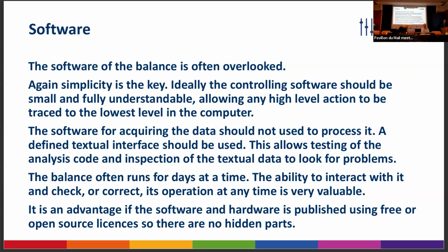Secondly, you shouldn't acquire data and process it at the same time. It's much better to acquire it, output it in a standard interface, and then do all the processing separately. So you can use several different programs and make sure that all is well, and keep the thing that's acquiring the data simple. Also, you've got a balance that runs for days at a time. If you can't access it while it's running, sometimes you get real trouble. I find the ability to interact with it while it's running and actually be able to change parts of it awfully useful.